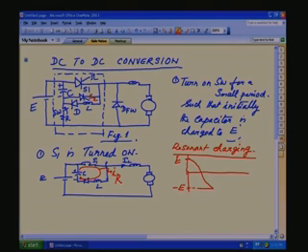So, what will happen to the current? If you see here, that IR current will slowly increase. At this point, current is maximum, so di by dt is minimum, then it will go like this. This is our IR. The moment current is 0, assuming an ideal LC circuit, the capacitor will charge to minus V here. So, this is our IR.